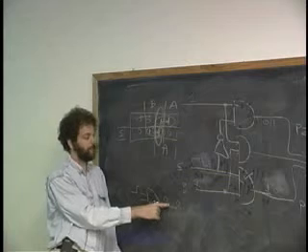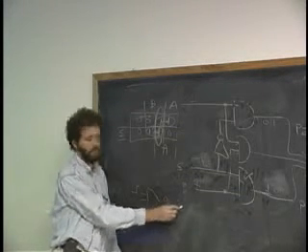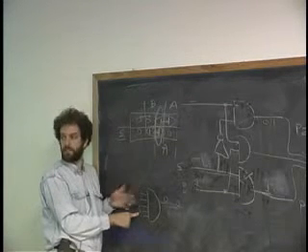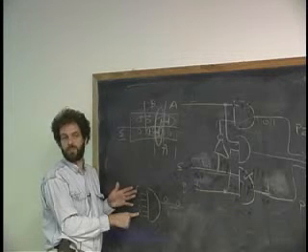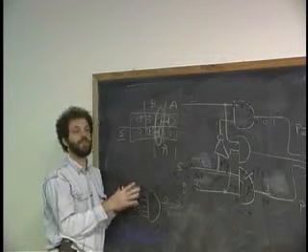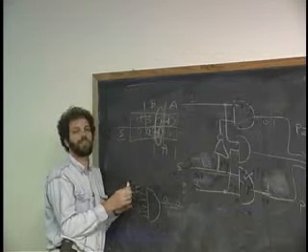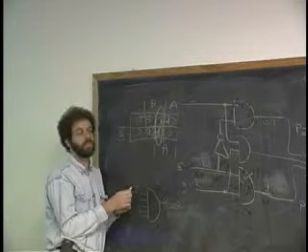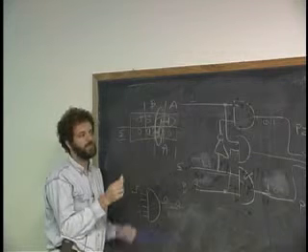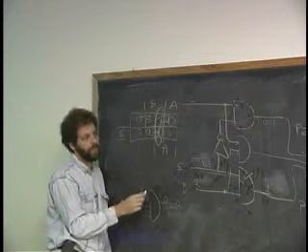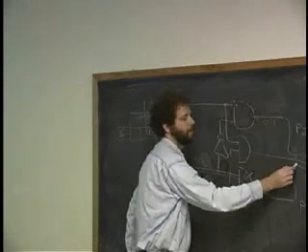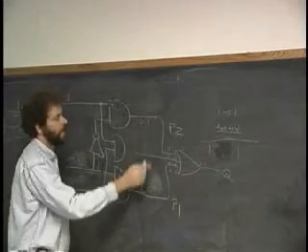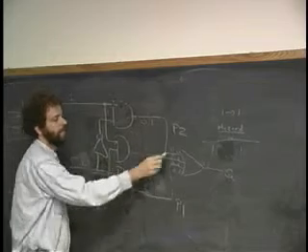So did this output actually change between these two states, or did it guaranteed stay low? If I have an AND gate and I hold one of the inputs low all the time, these things can wiggle up and down for all they want. Nothing's going to happen. So, as strange as it may sound, a sum of products implementation can never generate a 0 to 0 hazard. Okay? It can't happen. The final gate's an OR gate, not an AND gate. The final one's an OR gate, but to start with, everything was 0. Correct? Because the output was 0. And to end up with, everything was 0, because the output's a 0. And I just got through proving to you that for each one of these guys, they didn't glitch.